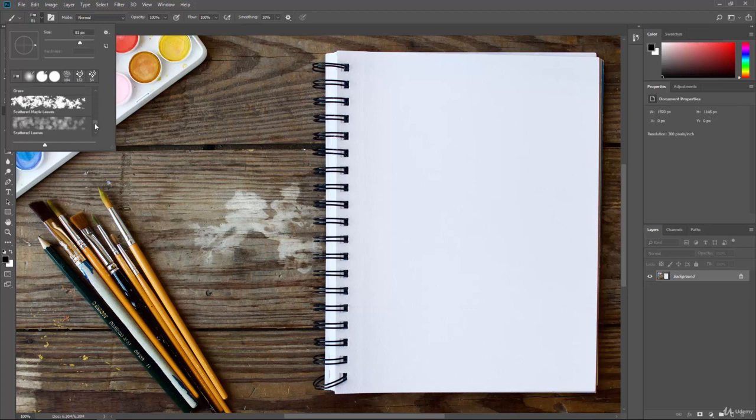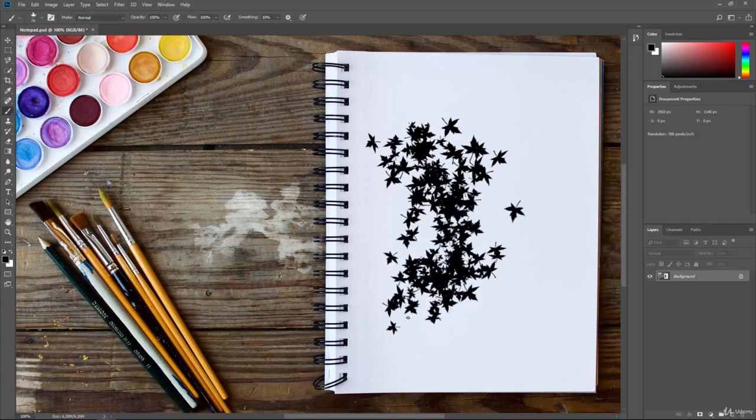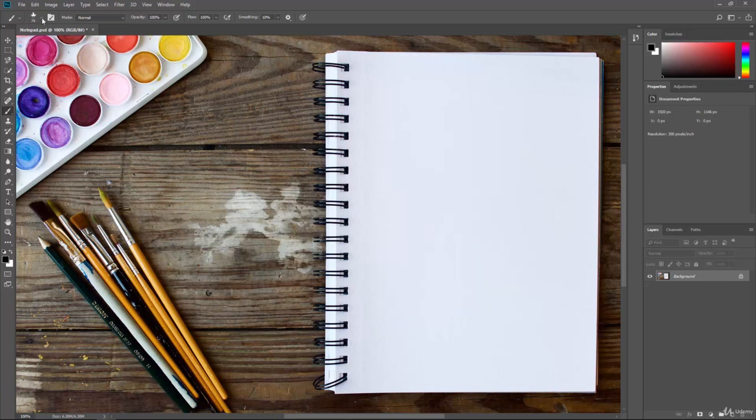And if you check your CCC subscription, you can see all the different brushes that they have in store for you. Here we have scattered maple leaves, this is kind of like the bird one that I'm talking about. Whenever I drop that down, it puts a bunch of leaves down, and we can change the settings on how they scatter and how big they are and so forth. We'll get a little more into the advanced brush settings in some later tutorials,